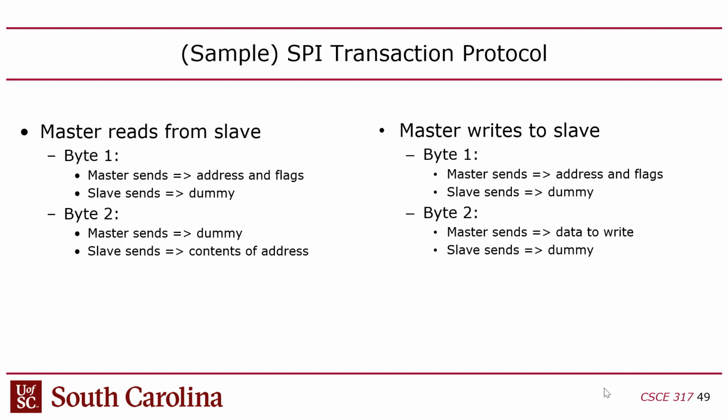Now there are other protocols, like I think an audio protocol, that take more advantage of the bidirectional nature. But when you're doing reads or writes, you just have to deal with the fact that you're kind of hacking the physical layer of the protocol, having to sort of bastardize it in order to perform this programmed I/O style read and write behavior.